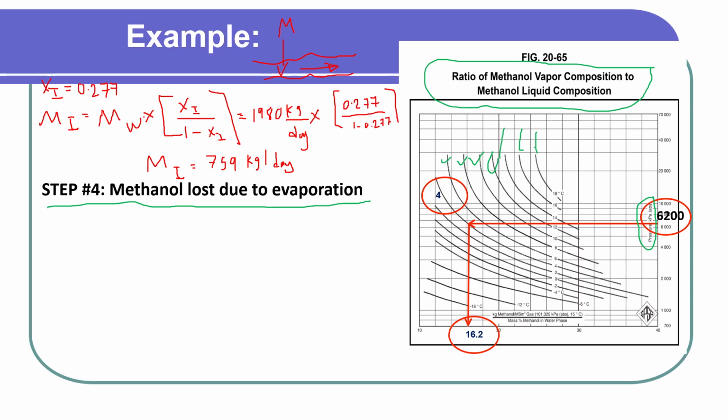Now I know how much the pressure is. The pressure that we need to deliver the gas to has a value of 6200 kilopascal. As we mentioned earlier, this is the pressure at the point where we are shipping the gas to, and the temperature at that onshore natural gas processing location will be 4 degrees Celsius. So I'm going to take this chart, the 4 degrees Celsius.